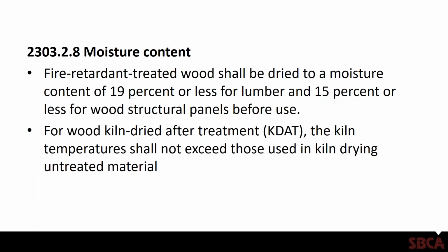Another thing that's critical with FRT is that the fire-retardant treated wood needs to be dried to a moisture content of 19% or less for lumber, and 15% or less for wood structural panels, after they've been treated.